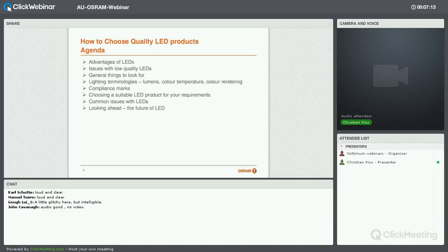Comparing products based on lumens and not wattage alone is basically the rule of thumb that you should look for when looking at LEDs these days. In the past, with incandescent globes, we had wattages, and there was pretty much no reference to lumens. So for a lot of people, lumens is a bit of a foreign term, and I'll talk about that a bit more on some other slides. But basically, to compare products, the first thing to look for is lumens. So you can see on the packaging if product A has the same sort of light output as the product B that you're comparing to.